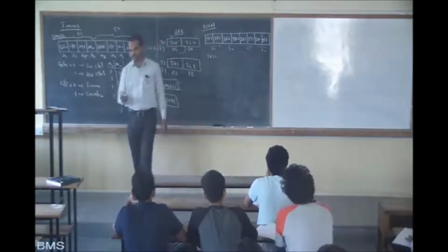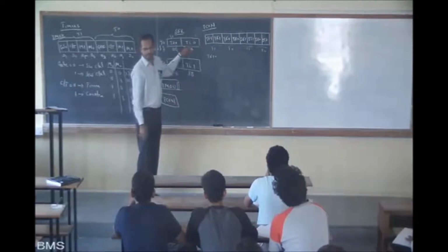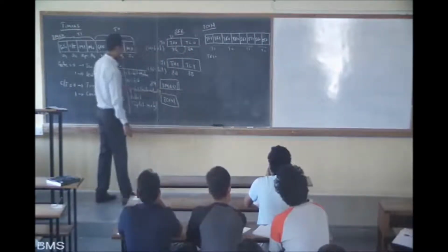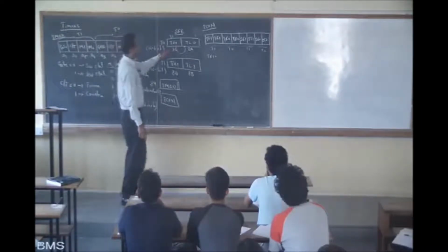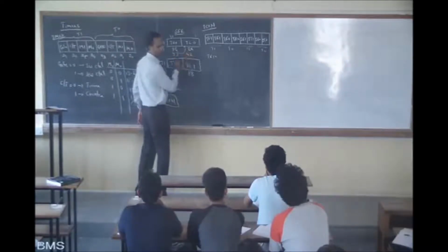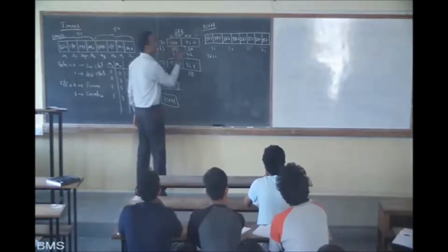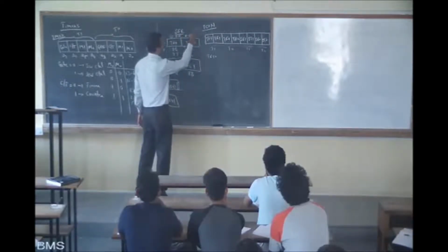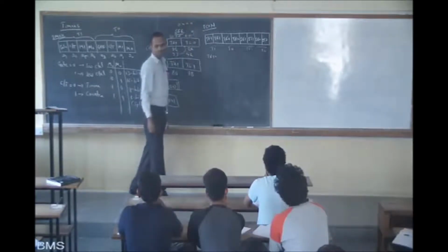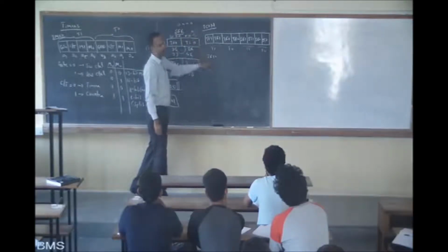What is TF1? TF1 is an overflow flag. Guys, listen to this. If it is a 16-bit timer, that is mode 1, it goes from some value that you have initially put, like let's assume 3342, up to the maximum FFFF. Once it reaches this, it will go to 0000. When it goes from FFFF to 0000, TF1 will become 1.